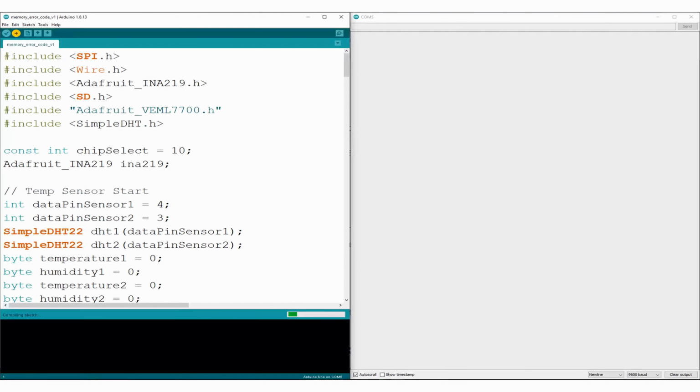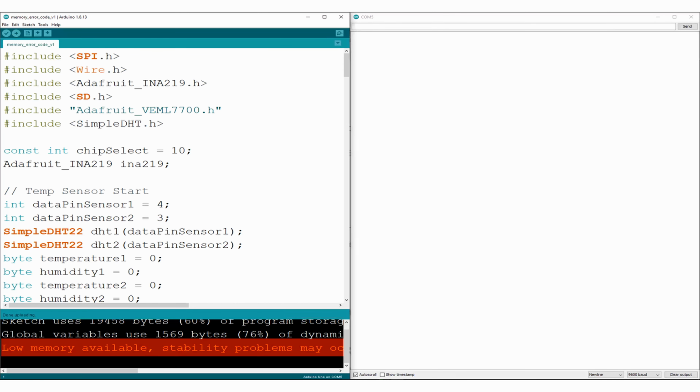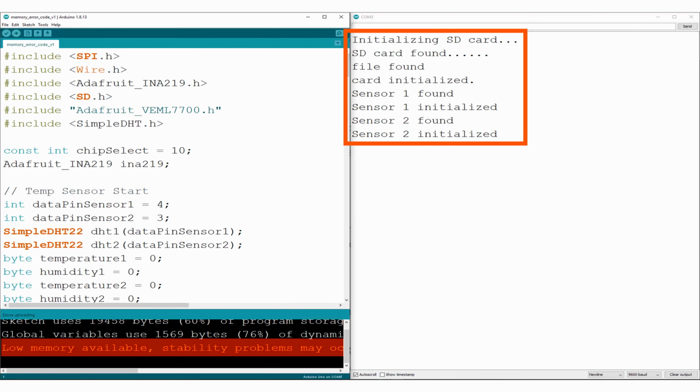We all enjoy using Arduino for our new next project, and it's one of the better platforms for prototyping and the debugging phase. In this stage, we often face low memory related stability issues. Most of the time, when we get this kind of warning message, the program compiles, but while running it on the microcontroller, it gets stuck at random stages and the code doesn't get executed. In this particular case, it never executed anything after the setup section.